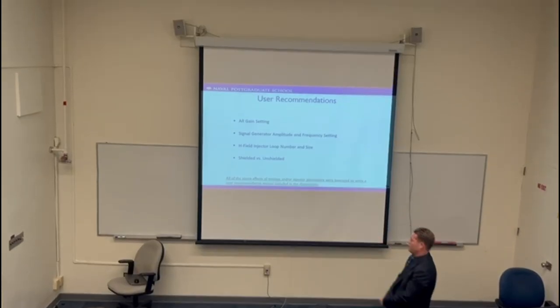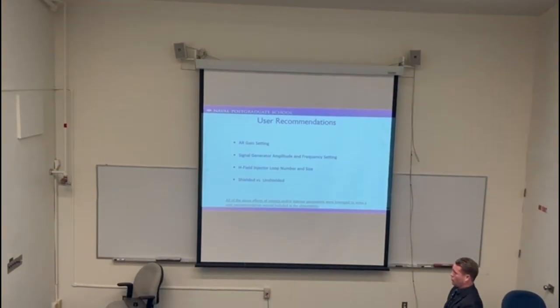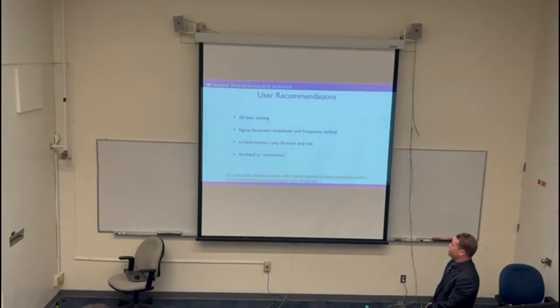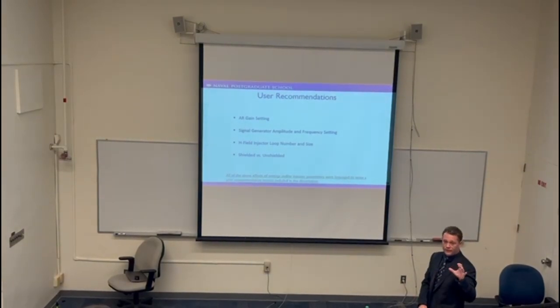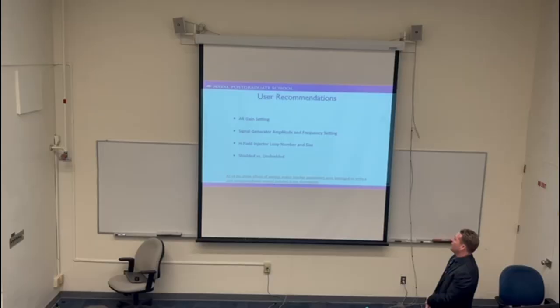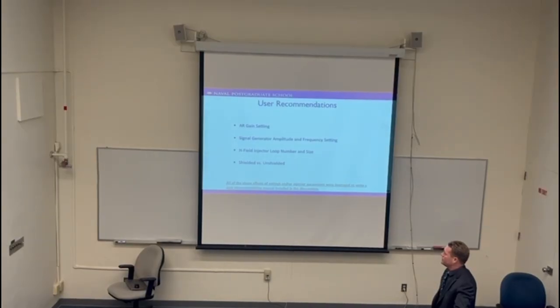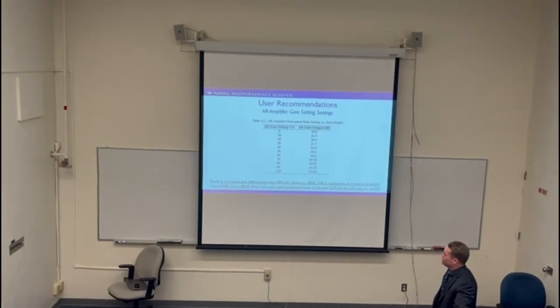So here's some of the things in the user recommendations that we're going to go over real quick. Here, the actual gain setting, the signal generator amplitude and frequency setting. Remember, those are the two knobs that they can turn to increase or decrease EMI. And then my H field injector loop number and size. That inductance obviously affects things drastically as well. And then the shielded versus unshielded.